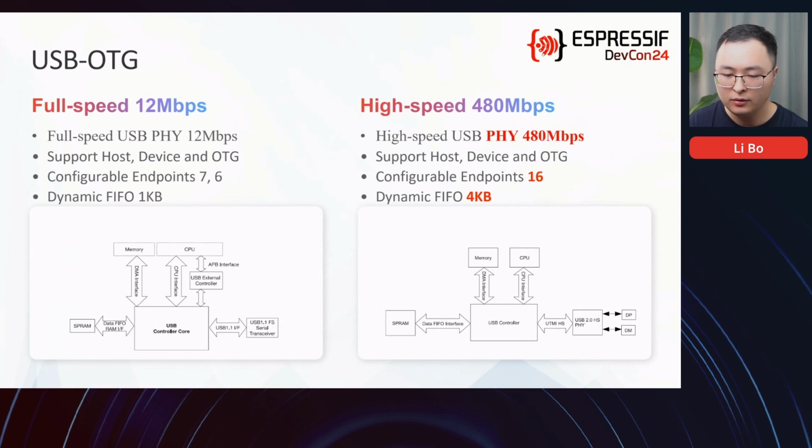So if you want to develop a USB device or USB host with more features, please select the chips with USB-OTG support. The S3 supports USB-OTG full speed, and the P4 supports USB-OTG high speed.